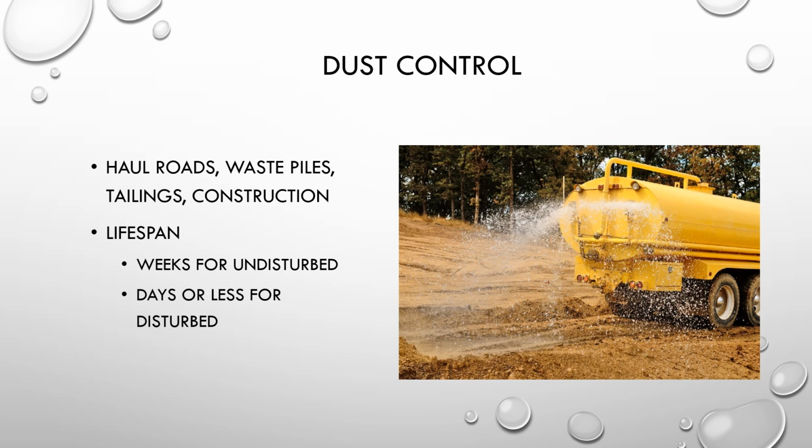And that single application, they were watering 10 to 12 times a day before the PAM application. So 10 to 12 times they ran the water truck over this road to keep the dust down. After the PAM application, it doesn't completely remove the need for watering, but they needed to water that site only one time after that one application of PAM. They watered the road every single day, and they did not need to reapply the PAM for 45 days. So the lifespan can really vary, and that one application lasted for 45 days, but they watered daily.